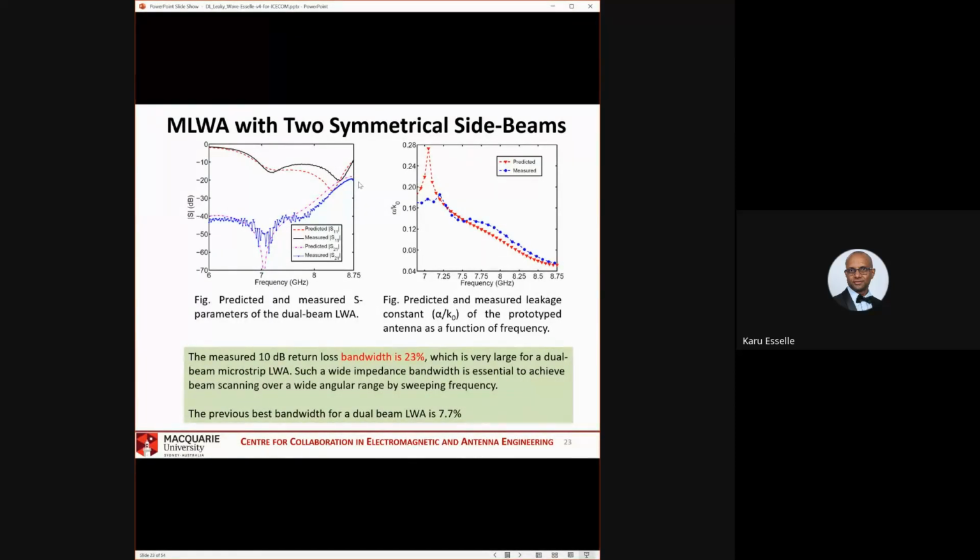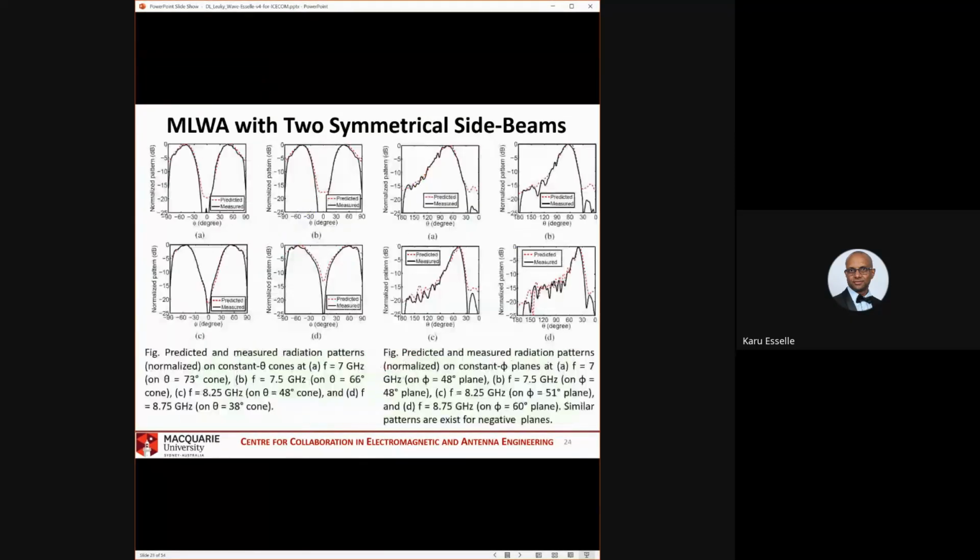So there's some power that was not radiated due to low alpha, and some power left over at the far end, and that goes to the matched load and gives this S21. At low frequencies, alpha is large, so it attenuates very well and radiates, and nothing is left when it reaches the match load.